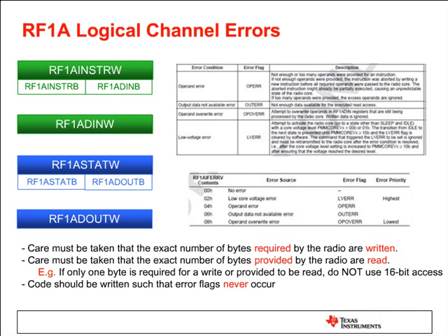It may not be ready yet, so we actually have ready flags on the radio that say, hey, I'm ready to receive a new instruction, I'm ready to receive new data, or ready to give you new data to read out from the mailbox. And you have to make sure that you're checking these flags so that you're not violating any of the timing of the radio as it changes between the states. We also have flags for that, right?